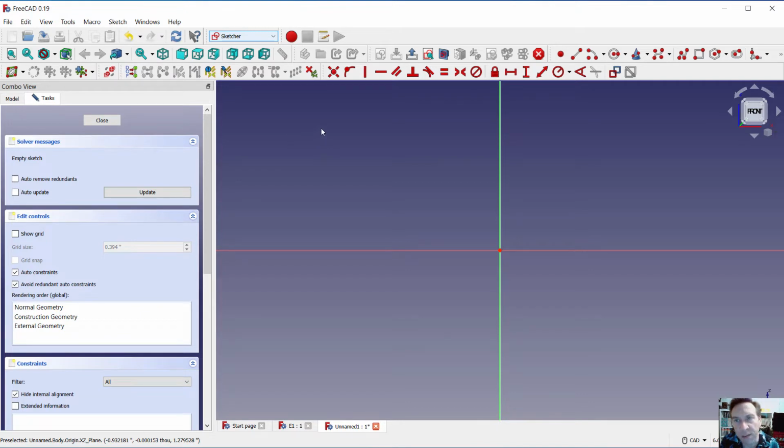But what we're first looking for is the rectangle tool. You see there are additional tools if you hit the little arrow there that pop out. We're going to be using those shortly. But let's go to the corner rectangle. Now find this point here. When the point turns yellow, when your cursor is directly above that little cross, click on it and drag it to the upper right. Click again. You'll see little symbols.